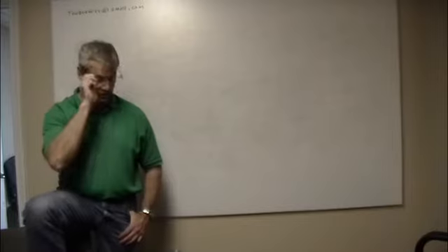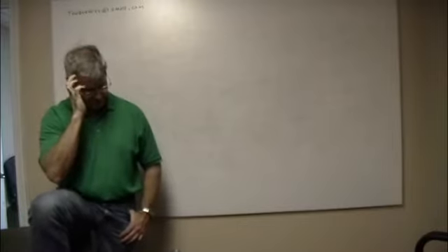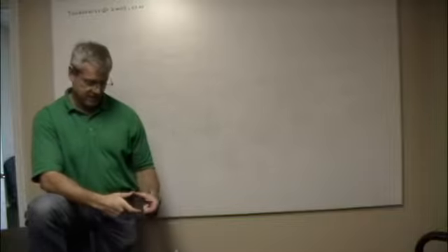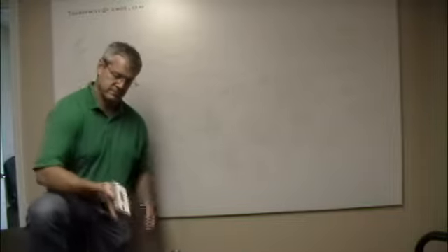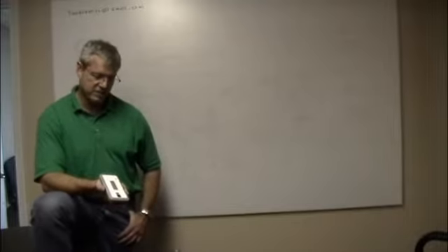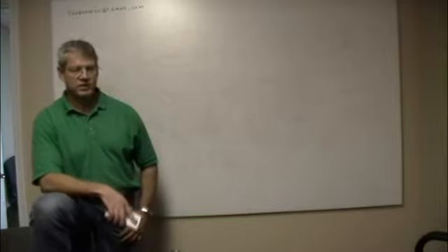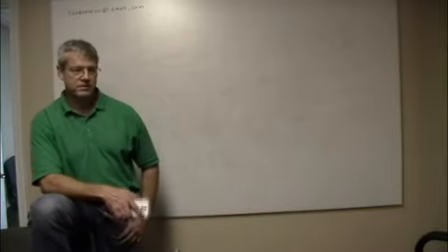I made a board for work a couple of weeks ago. It was about this size. I used OSH Park, which is a rapid prototyping house here in the US. You can get 2-layer boards back in like 3 days to a week.